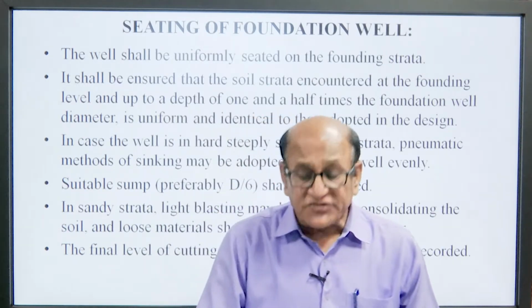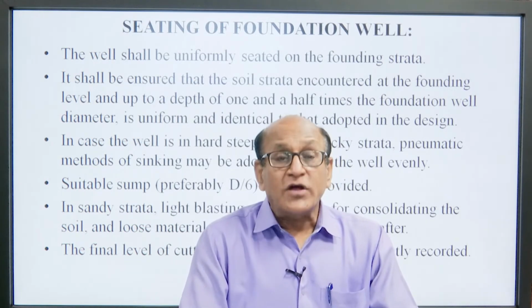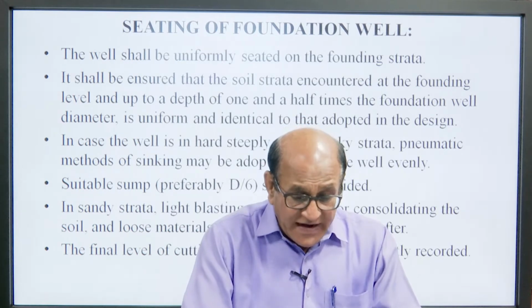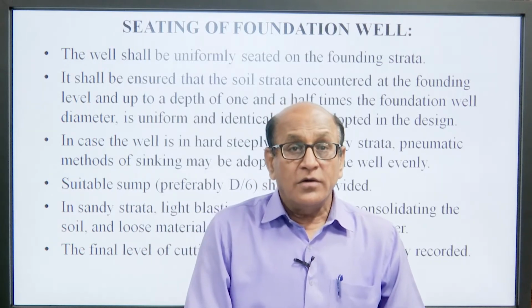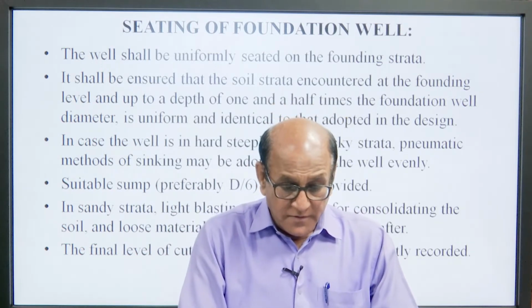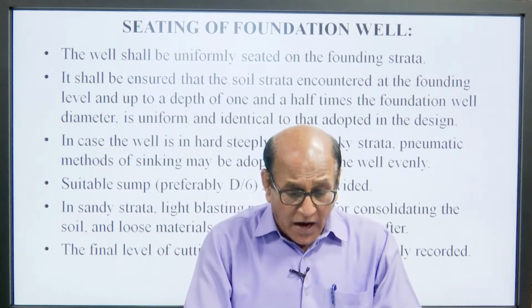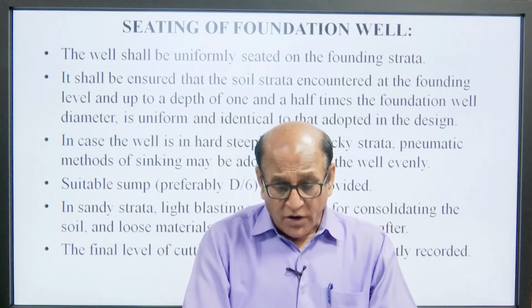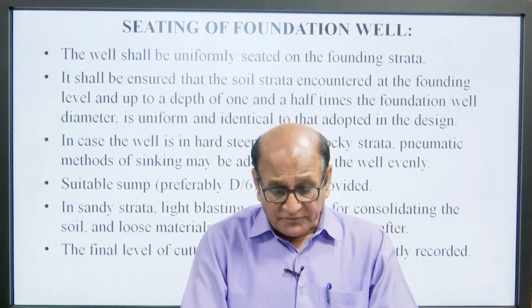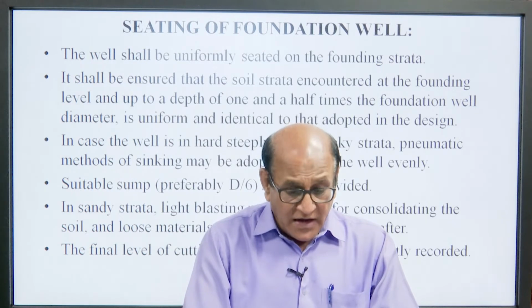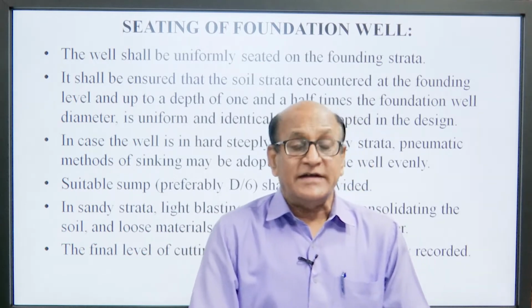Seating of the foundation well: the well shall be uniformly seated on the foundation strata. It shall be ensured that the soil strata encountered at the founding level and up to a depth of 1.5 times the foundation well diameter is uniform and identical to that adopted in the design.